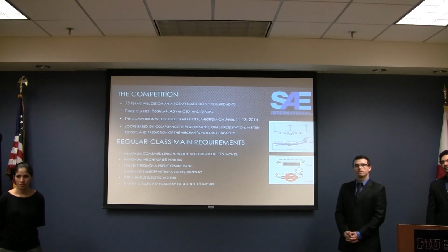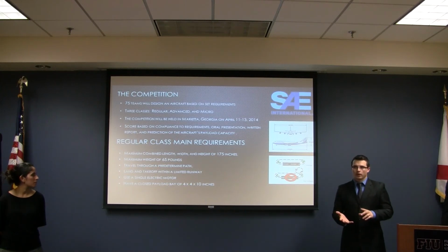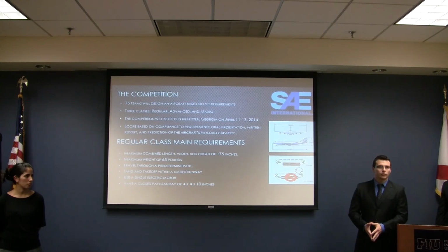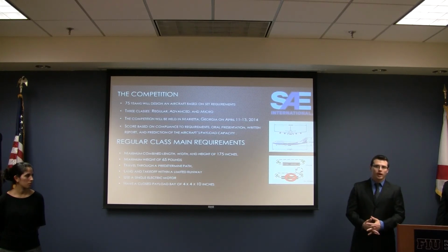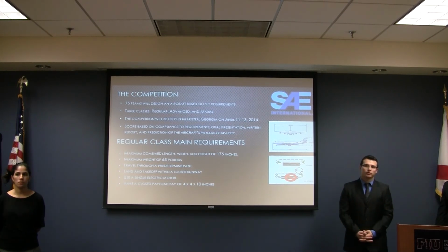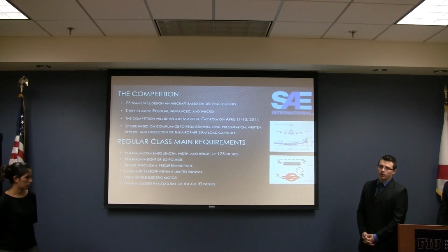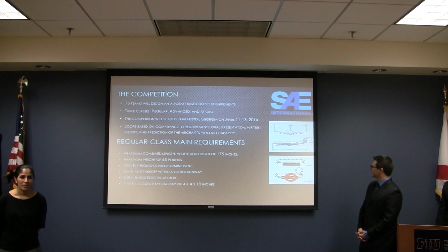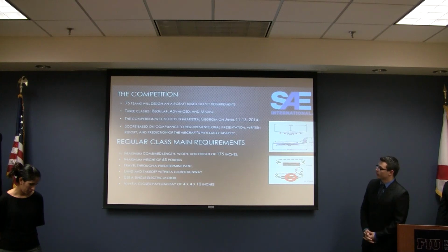And what are the restrictions for the competition, as in size restrictions? Well, on materials, we have restrictions: you cannot use composite materials. We can only use one propeller as well. The engine has to be electric. We have a power limiter of 1,000 watts or 200 amps. That's part of the restrictions of the competition. We have 20 pages if you want to read about it. As well, the runways that we use, the length for landing and for takeoff, is a very limited factor when it comes to the design.